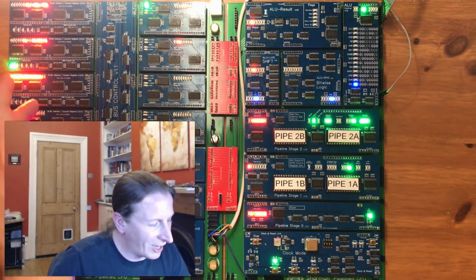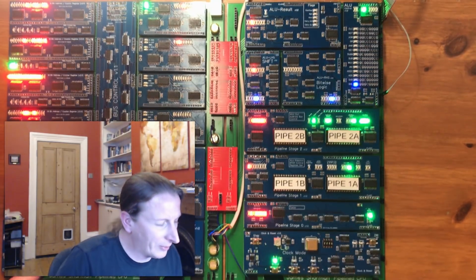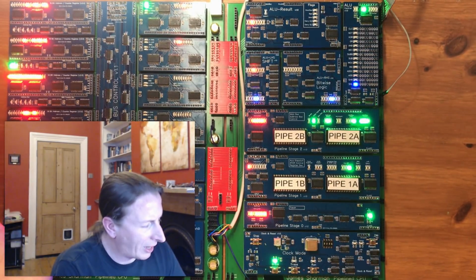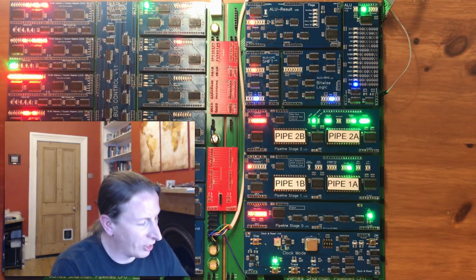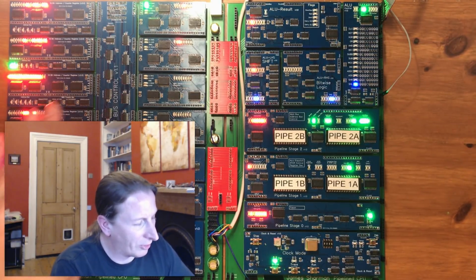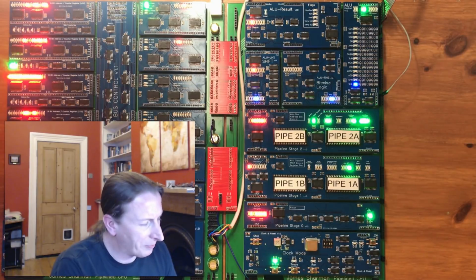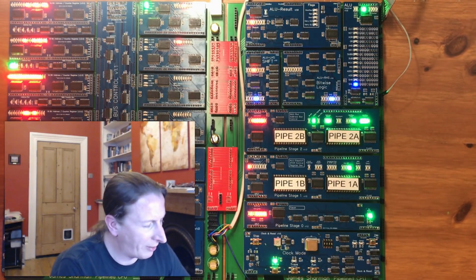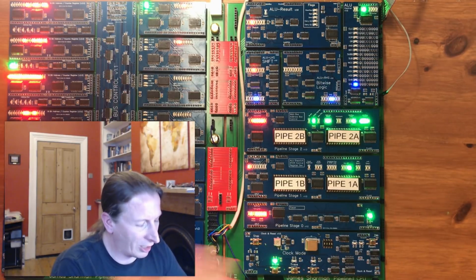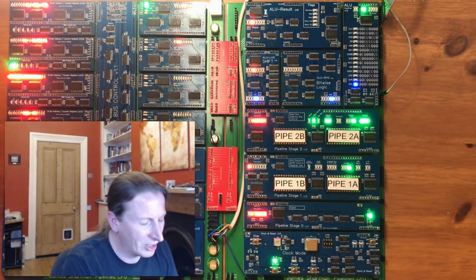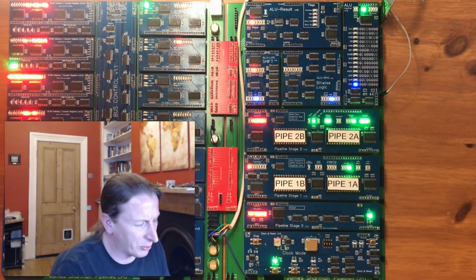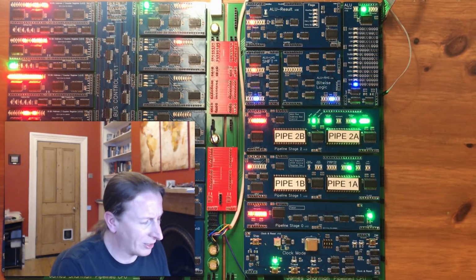So I needed this extra bus that was 16 bits wide. Now I did have a thought for having that operation done over the address bus, which would have removed that bus completely, but that would have meant that a 16-bit move operation would have taken up the address bus and it would have dropped me an instruction. It's difficult to know exactly what the performance impact would have been, but it would have been an impact.